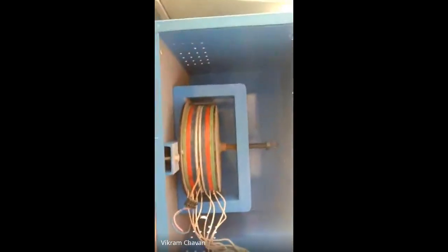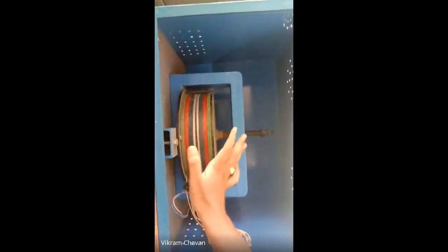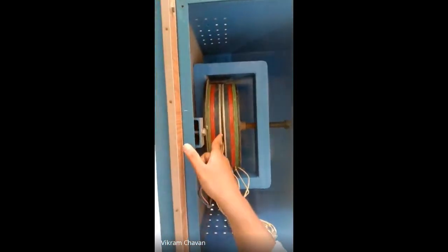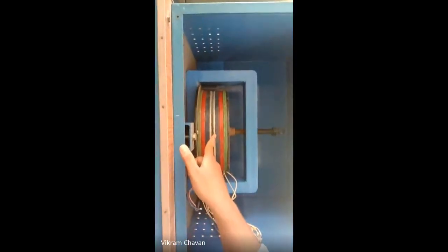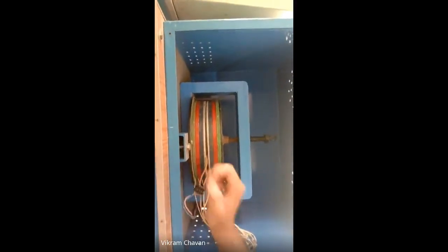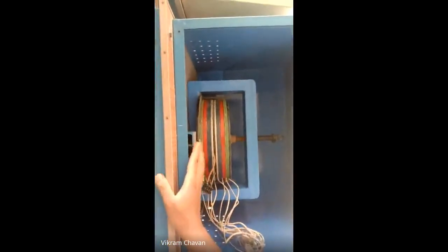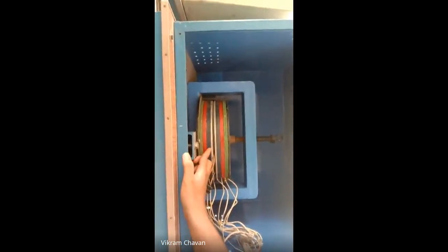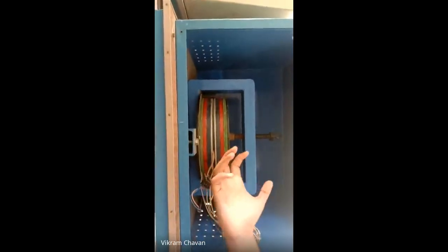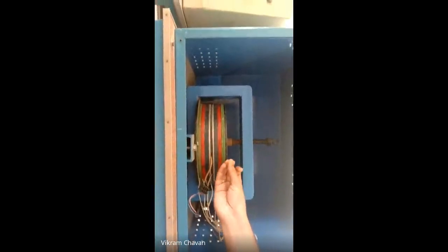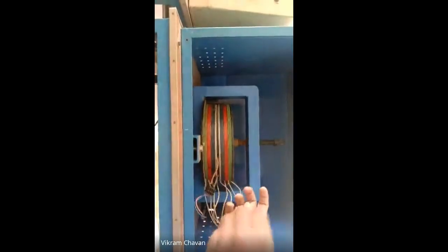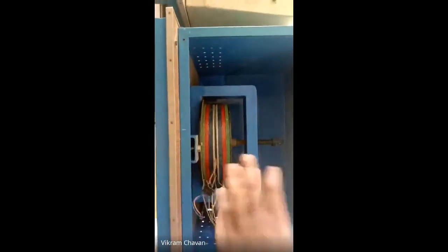Okay. So this is the composite wall. You can see here this is the heater wire, and the heater is placed in between two aluminum plates. These white plates are nothing but the aluminum plates, which have 6 mm thickness. First of all, the heat will be transferred to this aluminum plate, and aluminum has higher thermal diffusivity and also higher thermal conductivity, so it will receive the heat from the heater, it will get diffused and it will transfer to the next slab of that particular composite wall.